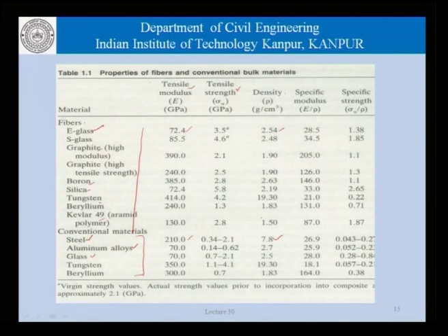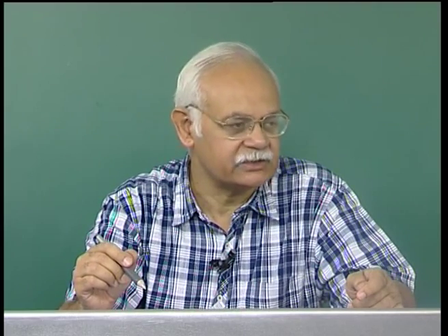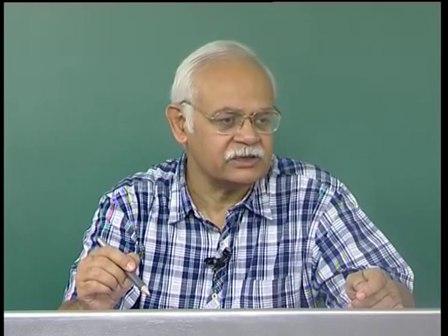So, this fiber is approximately 1/3 as far as density is concerned, and is also about 1/3 as far as the modulus of elasticity is concerned when we compare the performance of e-glass with steel. Steel being the conventional reinforcement and e-glass being a non-corrosive alternative, which we are considering for application in structures where corrosion could be a severe problem.